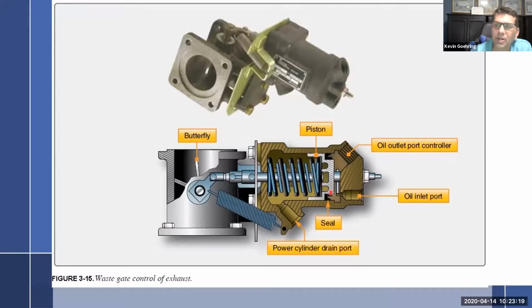You just have engine oil pressure, and you drain it off. So oil comes in, and if I have a cap right here, as soon as you build up oil pressure, it's going to make this close, turn on the turbo, and it will always be on. And if I unscrew the cap, then oil comes in and drains out of here, and this would open. So it kind of works that way.